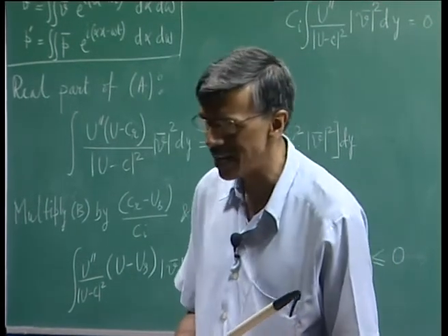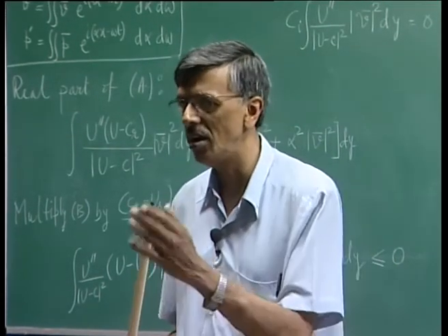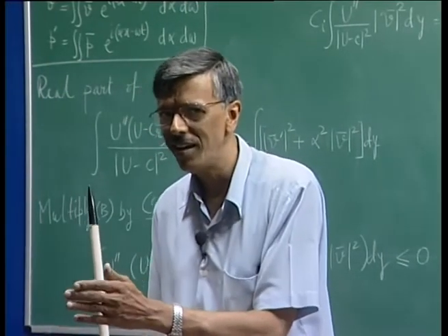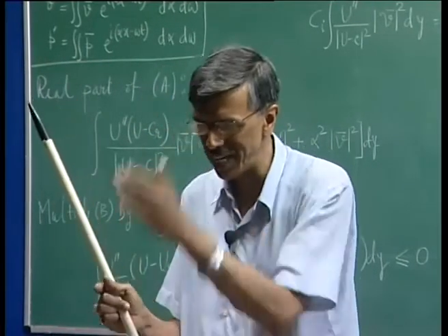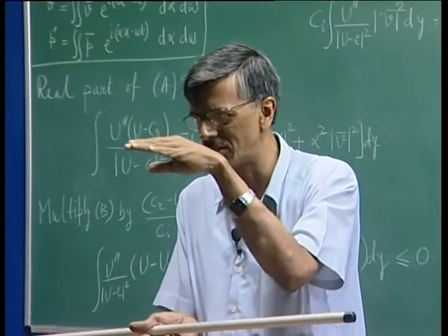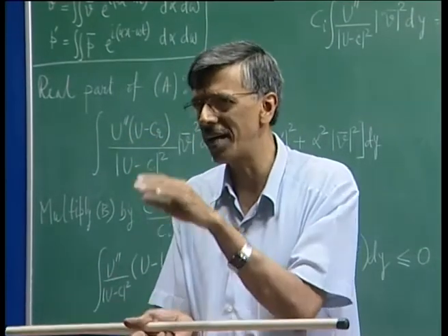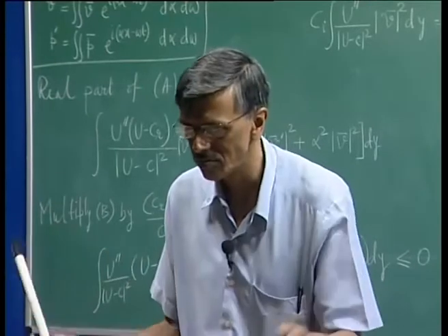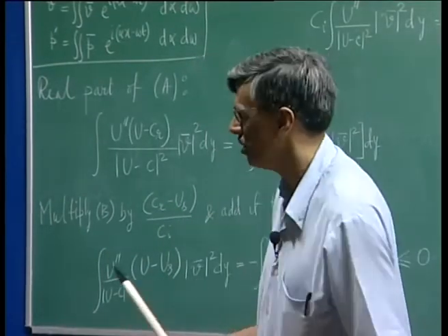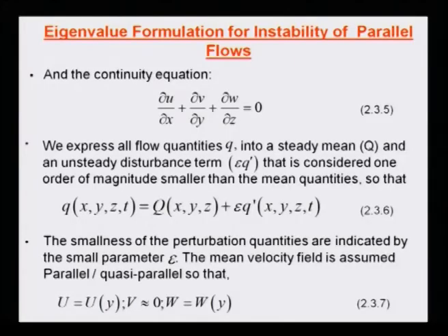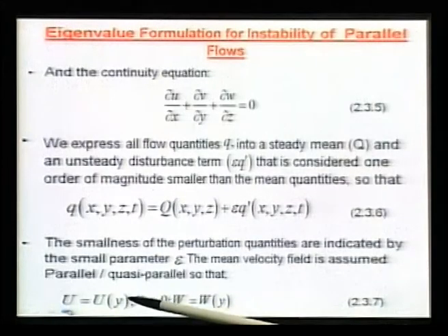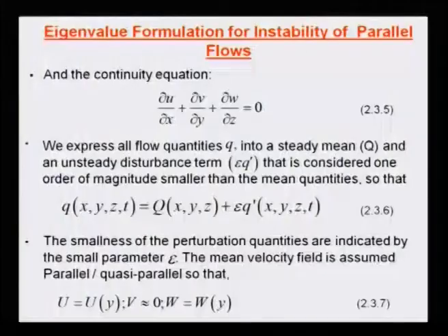But if the growth is negligible, I can still study the flow locally and say, look, if I am studying at this station, I take the velocity profile, the dependence on x is weak. So, let us omit that part. So, basically what we are saying is that in the argument list, we should have a y comma x, but the x dependence is much weaker, it is a stronger function of y. Okay. That is what is called a quasi parallel approximation.